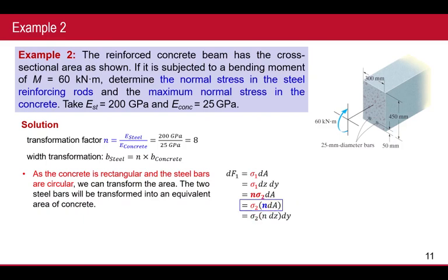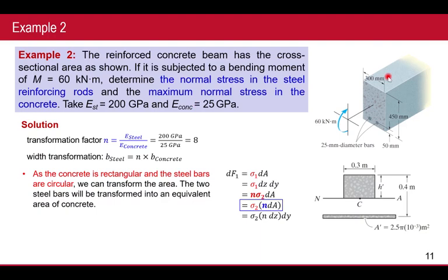So that's why from here, we can go this way. Concrete, steel bar, we can use concrete as a rectangular one. But remove this part because this part cannot sustain tension. So there's no meaning to put these things for concrete under the neutral axis. Everyone clear? So that's why from here we can get these things.